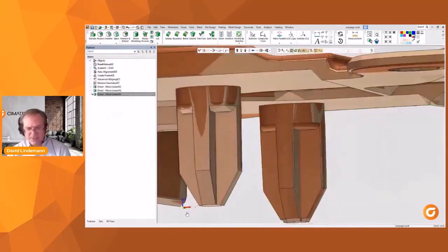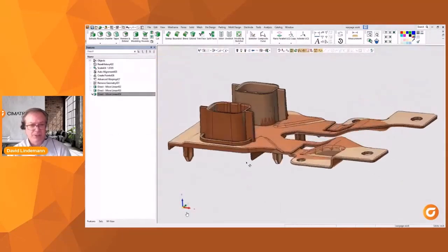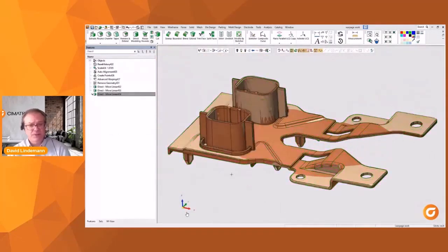So like we said, there's a lot that goes into dealing with warpage, and no two parts are the same, and there are different causes for the different warp conditions we measure, right? We like to know what those causes are so that we know how to attack the situation. But here, hopefully, you've seen some tools that greatly take down that workload. We can look at the draft angle conditions and deal with those. Also, we can deal with all these different positions, the way the part may warp, and we can capture that, reverse that, now save that into a CAD file and make little tweaks along the way if we desire.